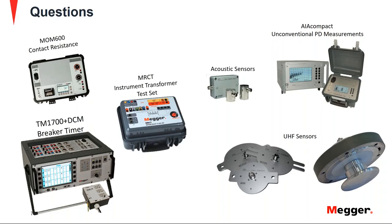You measure that current at the CTs of the system. So the main CTs on the primary side of the load of the breaker, you connect your ammeters or your little CTs to measure the secondary current. And when the breaker is tripped, those CTs are going to detect, or you're going to see, that the current disappears. So that is the moment that the breaker has opened. So it's an indirect method to measure the timing of a breaker.